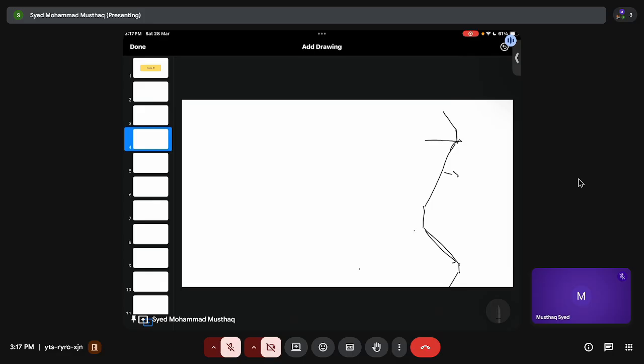At first you will have a stock line. There is a head from where there are different types of charging. There is bell-less type charging. We are not going deep into the iron making technology, because there are different courses for that. You can have one lecture just on the charging of iron ore and coke itself, because that much technology has evolved over the past few decades. There are different types of charging: bell-less charging, bell charging, and rotation type charging.